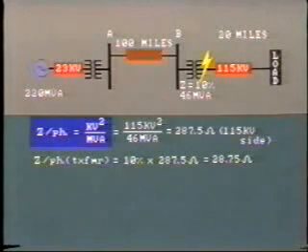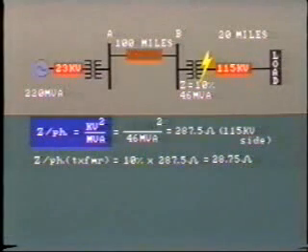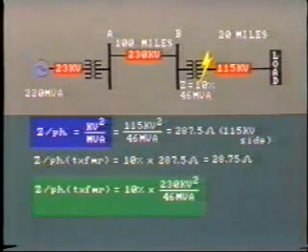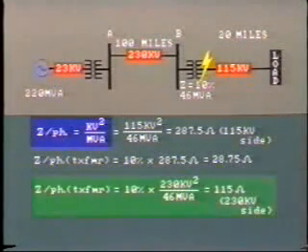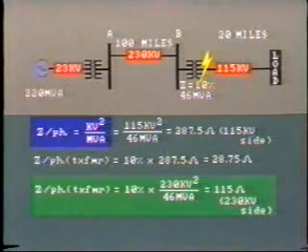But wait a minute, we may just as well have inserted the 230 kilovolt value for the transformer voltage instead of 115 kV. In this case, the ohmic impedance would come out to 230 kV squared divided by 46 MVA times 10% equals 115 ohms.